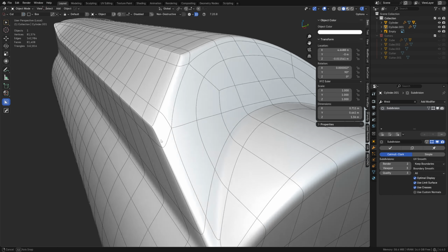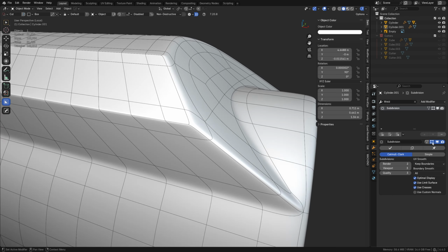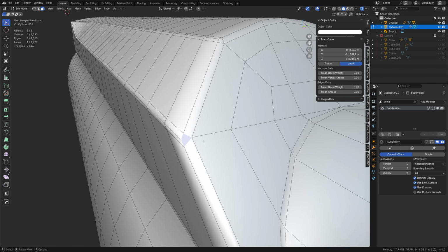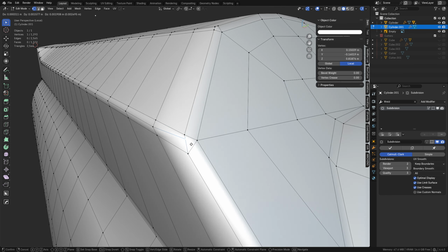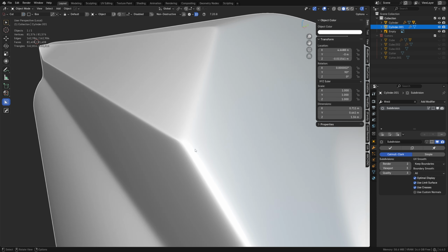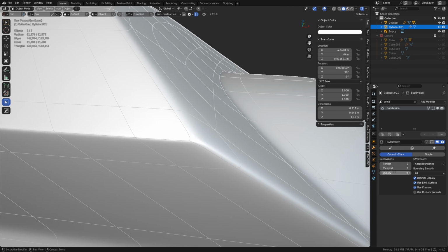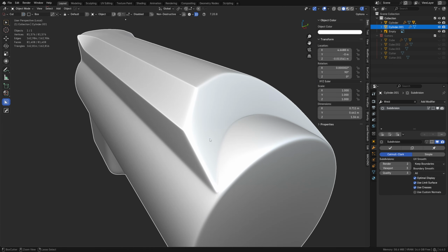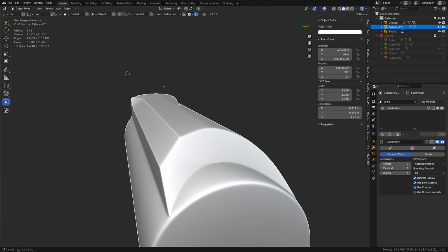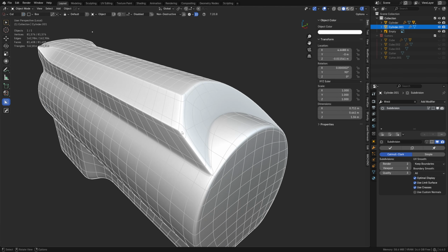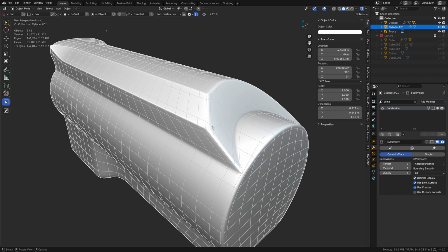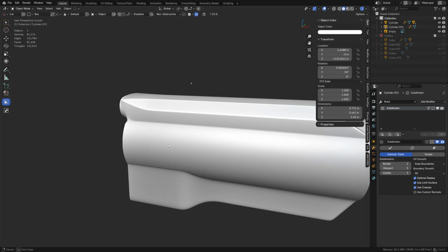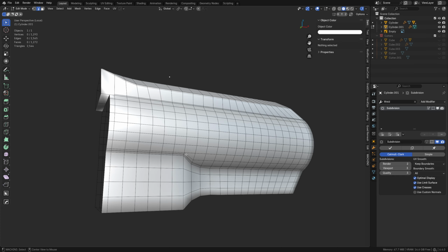Okay. This is why sometimes having those poles, when you create that, this triangle or this triquad, it behaves like a triangle because it has an end pole back in the backside of it. But it creates a little kind of pinching point in here, right? Sometimes it's not too noticeable. Sometimes it is. In our case, I think it does okay, but you want to be aware of that. So that's why you would push it further down into this face by overextending it like I did at the start there. All right, now this is a little bit softer, which is nice. This is a little bit softer down here.